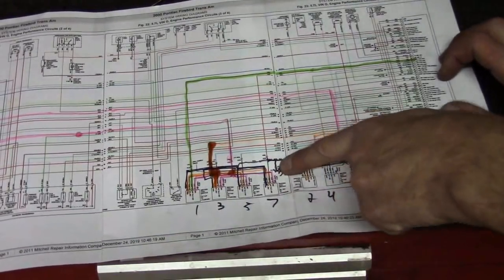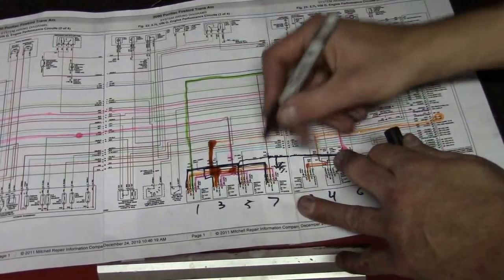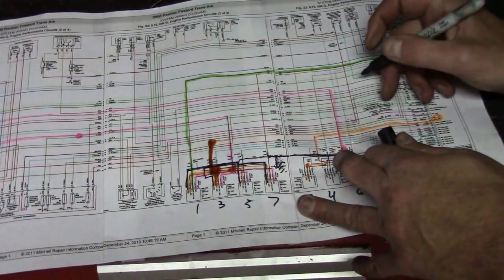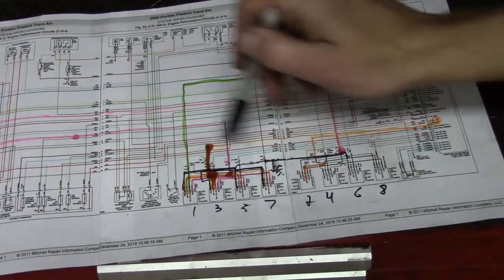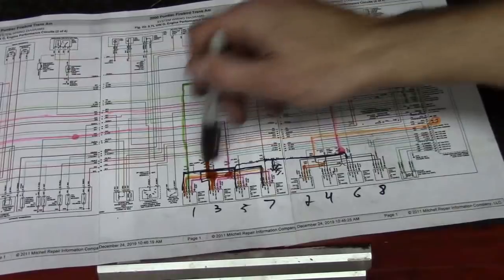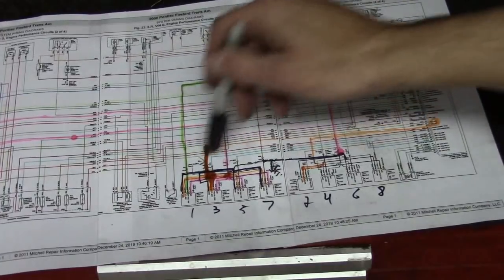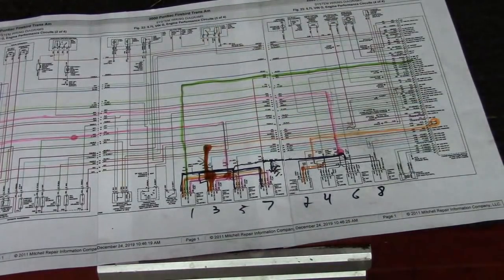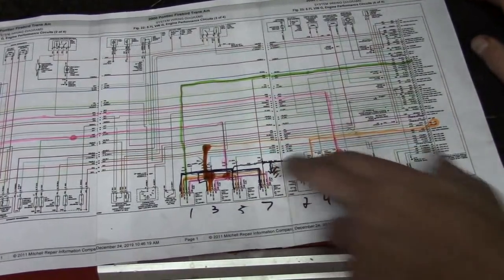Right? There's our common ground. So we could measure that parade with current wherever it was easiest. We could measure it at this common ground. We could measure it here. Okay? So that actually is more tools in our tool chest that, again, if we had an engine design where we can't access the coils, we have two potential sources where we could take measurements on the ignition and determine whether we need to take an intake manifold off or not. We actually have a couple sources there.